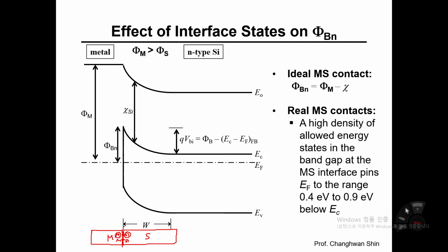The theoretical limit is approximately 10 to the 10 per square centimeter, but it's very tough and not very cost effective. So in industry, process engineers would control and monitor in real time the total amount of interface states below 10 to the 12 per square centimeter. Then that's good enough. So that is just for your information.